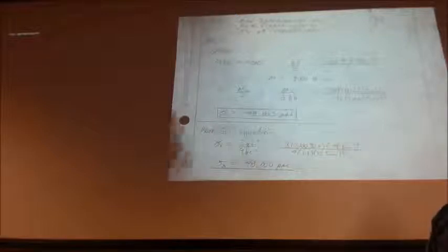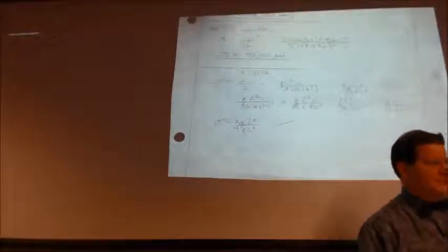Now if we use his equation, I get 48,000 psi as well. So how did that happen? Well, if we substitute the QL squared over 8 in for M, do some algebra, and substitute in C for H, we can end up with his equation. So you can see that it works out. And we can do the same thing for at least the deflection portion of the equation, or the bending, I mean.